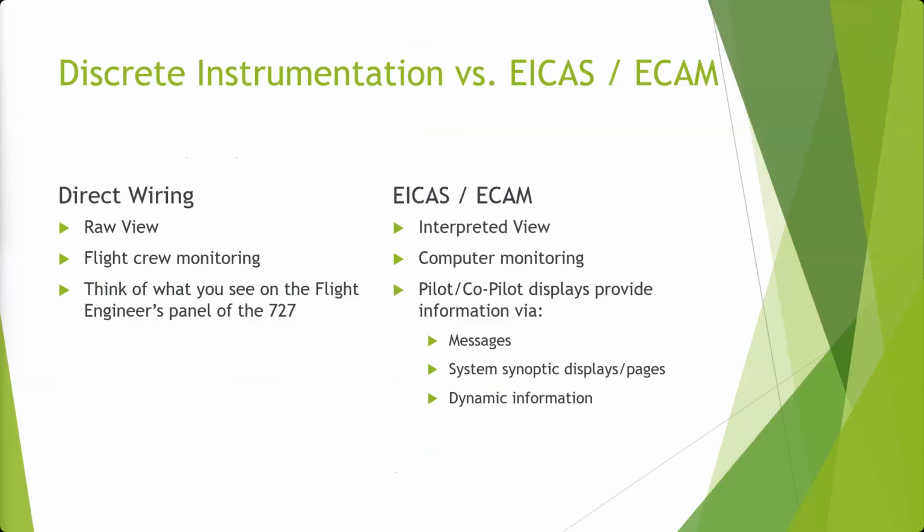Right? That's all interpretation of different data that's being fed in, rather than a gauge that just reads the hydraulic pressure is 3,000 psi, with a pointer pointing at 3,000, or if it's low, it's pointing at 0, or if it's in the middle, it's pointing at 1,500, right? So you did have some of that, typically a low pressure light or things like that as well. But again, those were raw. That was usually a pressure switch feeding a light rather than taking a pressure transducer and deciding, is this low or high? Right? That was done by a human when you had a flight engineer.